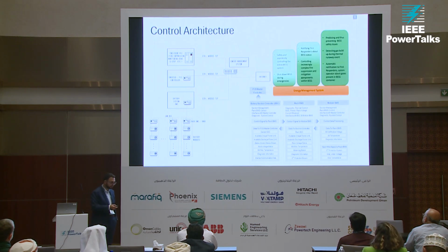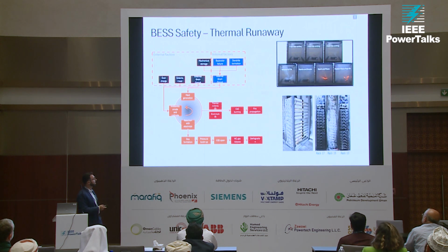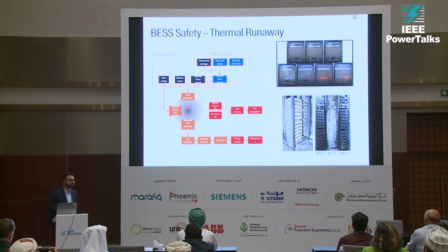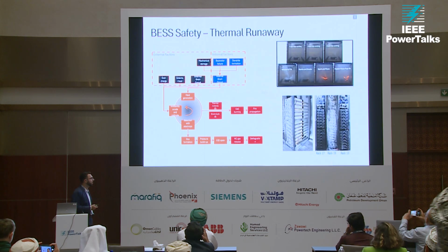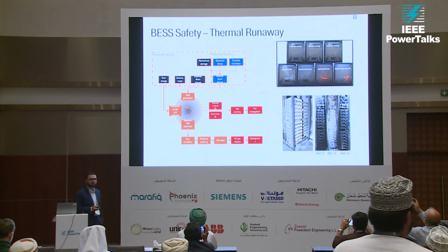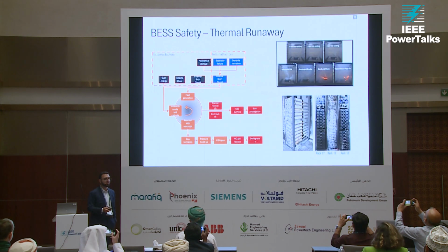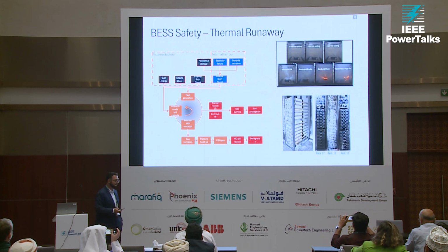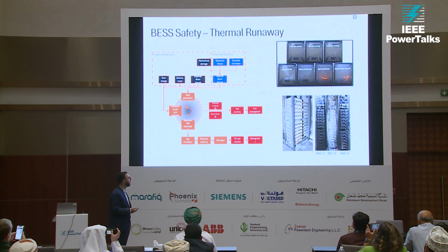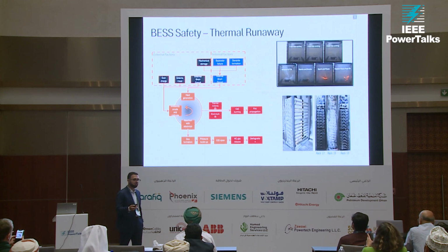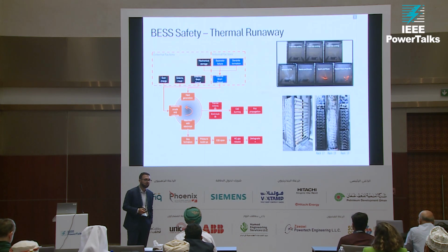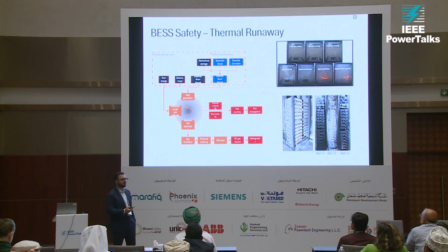We talked quite a bit about fires, and these are becoming a very interesting topic in the industry. Recently in the US, we had a few large fires. Some of them resulted in deaths related to battery energy storage systems. Most of the fires, as I mentioned, are related to NMC batteries, and in a lot of the incidents, the conclusion is people did not have the proper training.